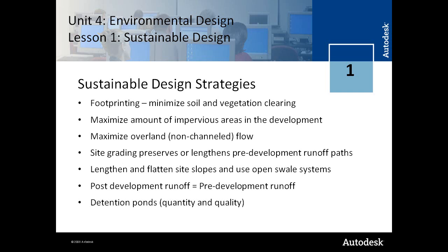There are a number of sustainable design strategies. Footprinting means to minimize soil and vegetation clearing and incorporating those natural elements into your designs. You want to maximize the amount of pervious areas in the development, so green spaces to allow water to infiltrate into the ground.